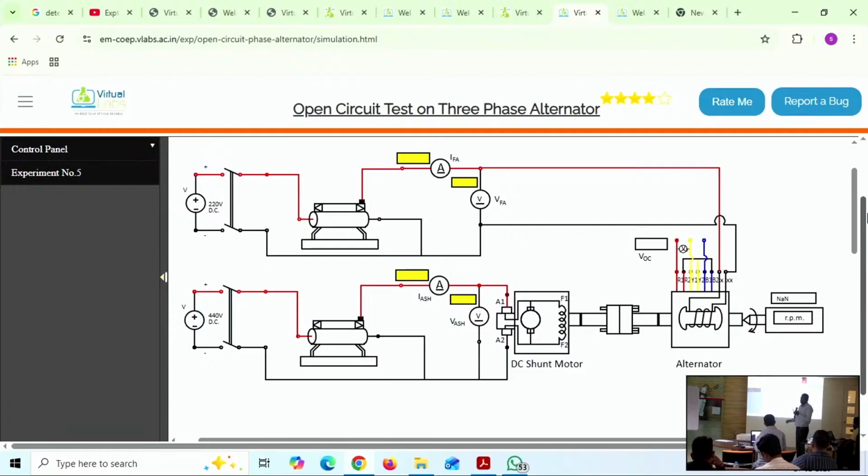We will clearly know that. Keeping those points in view, when we are doing the experiment, some value is shown. The student immediately asks, sir, we did not give anything, IF is at 0, so it should start from this value, but it is showing some value. We may say, okay, meter errors or something else. In the initial days, I also used to escape the first time, but later I used to think, how is that coming? I did it again and again, then I started learning that there exists residual flux.